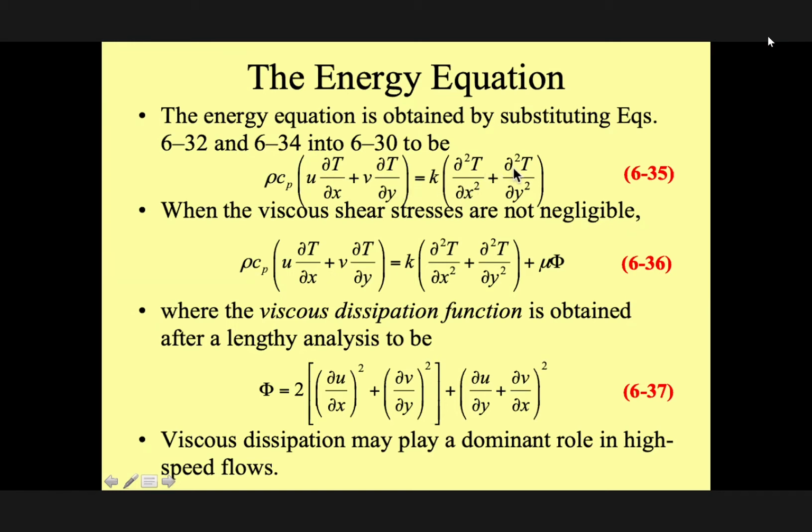Again, I'm not going to ask you to solve it, but at least to know how this equation ended up like here. We wrote a simple continuity equation, momentum equation, and energy balance equation. The reason we need the continuity equation is to be able to find a relationship between these two velocities and replace them here, okay? In order to do that, we have to solve the continuity equation and momentum equation to be able to relate these two velocities together, okay?